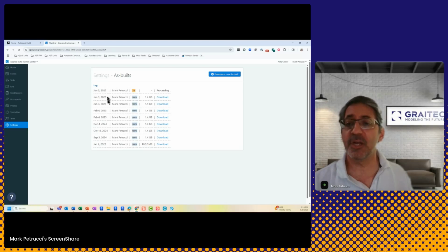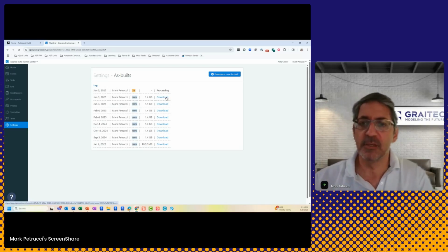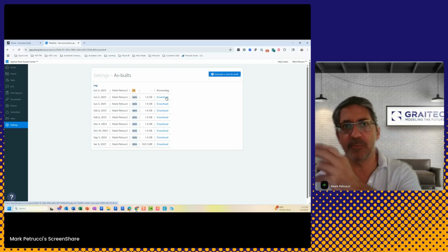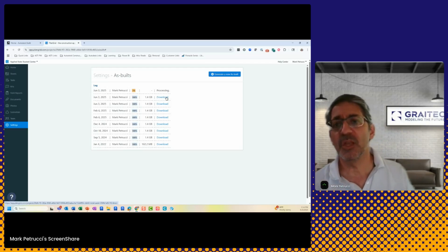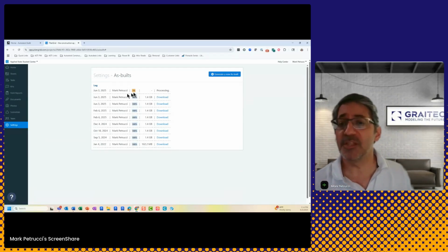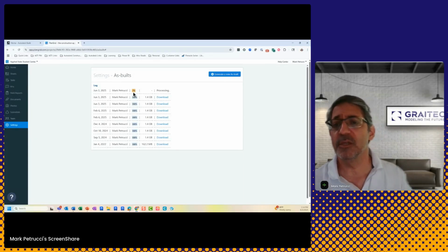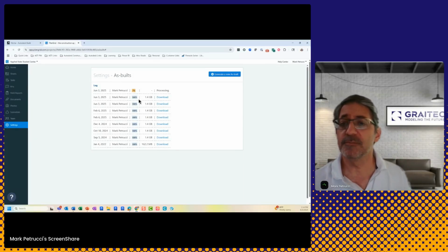Now, I've already done this a couple times today, and if I wanted to, I could hit the download button, download it to my computer, and then go over to ACC and upload it there. But I'm going to use Bridge. I don't have to do the download and upload. So this is all I'm going to do here. Now, this one's going to take probably a good 5 minutes to run, so I'll pull in one of these others. But I just wanted to show you how easy it is to generate an as-built set.